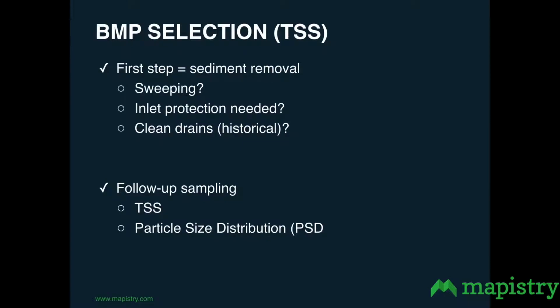You may get pushback from different regulators on potential groundwater impacts, runoff impacts, those types of things. So look into that if you're using dust suppression chemicals. But what can you do in terms of a paved site or even just packed gravel? Sweeping is probably the best BMP out there. Second, looking at potential inlet protection. That could be filter socks, it could be inserts, those types of things can really help from a sediment perspective. And then clean out your drains.